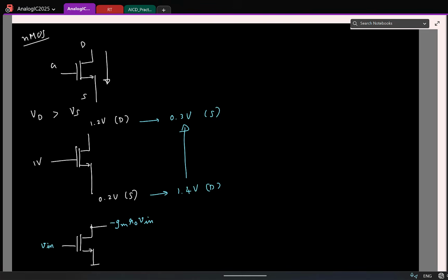again only for small signals, right? So let's say this is minus 1 volt. Let's say I get minus 10 millivolts here. So now it looks like this is at minus 10 millivolt and this is at 0 volt. Do you think now the source and drain have interchanged? Already? Remember that we are only looking at small signal voltages, but the total voltage is the small signal voltage plus the operating point, the bias point.